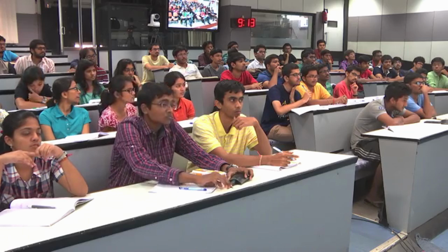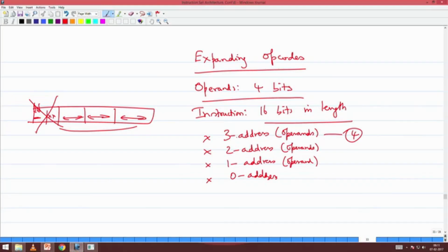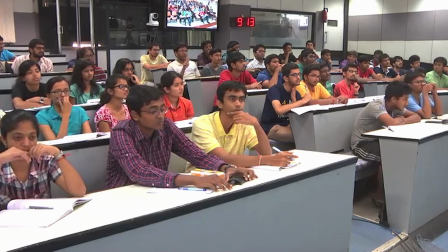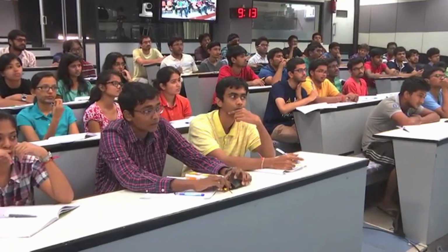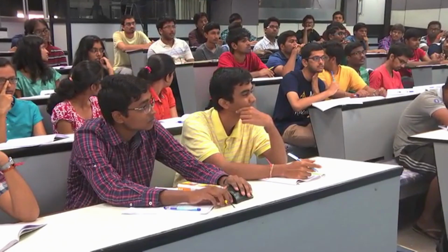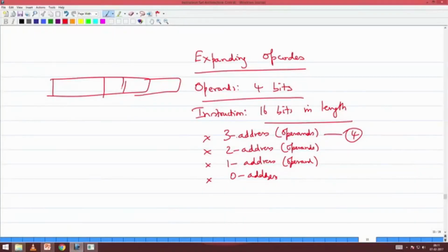So essentially what he says is correct, but that's not optimal. Okay, now can you start your solution? If you are using 3, then we will take only 12 opcodes, 12 different operations. So if I have 3 address instructions, 4 bits will be left.